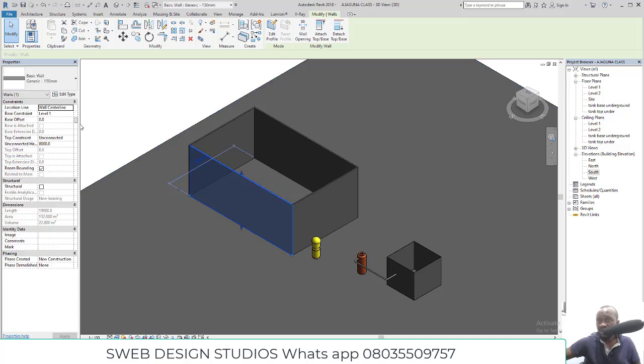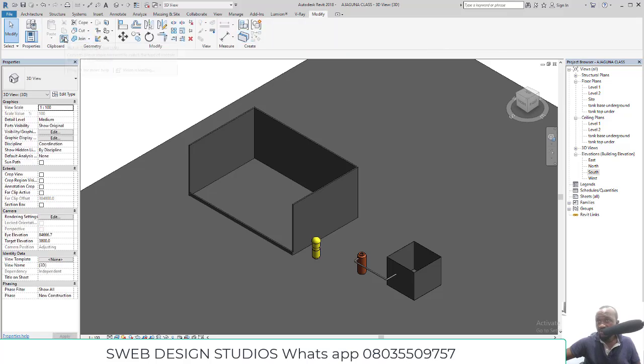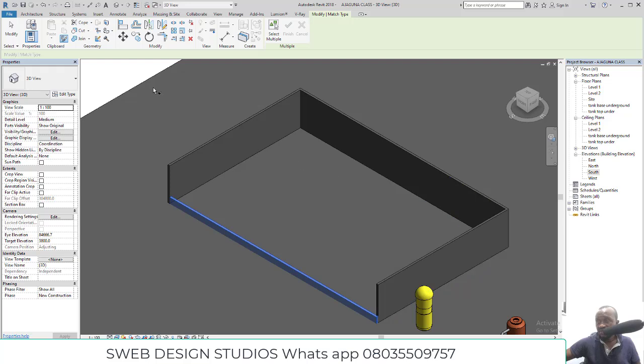Once I select this wall, I'll set the base constraint. Now the base constraint will be tank base. Okay, then the top constraint will be tank top. So it makes it very easy to just put it the way you want. Then I can just come to this match property, select it, and select this one first, then select all the ones that will carry the same.